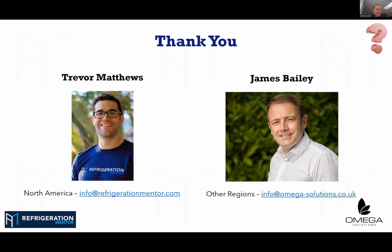Trevor, just to add to that, I'm really agnostic. I think there's a place for all refrigerants, bar HFCs. I think there's a place for HFOs. There's obviously a place for naturals, but a big advantage of CO2, you've hit the nail on the head. One thing as a design engineer, you've got no glide with those refrigerants, so that's another plus.